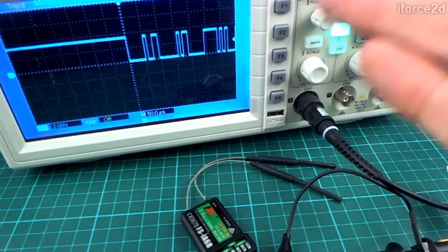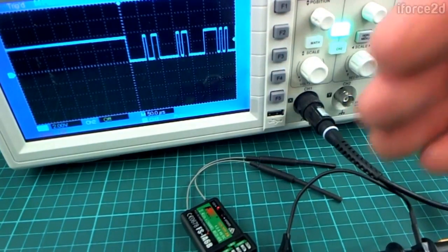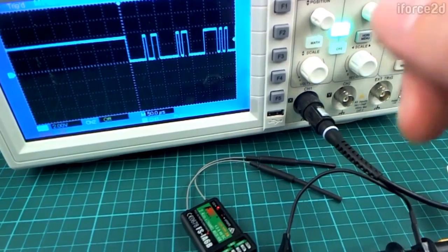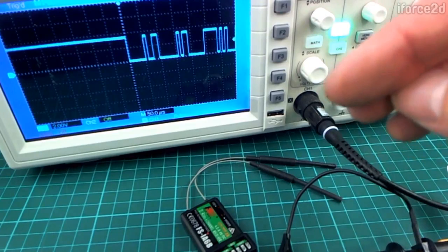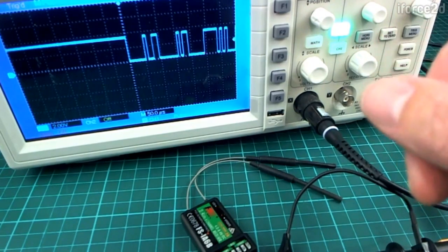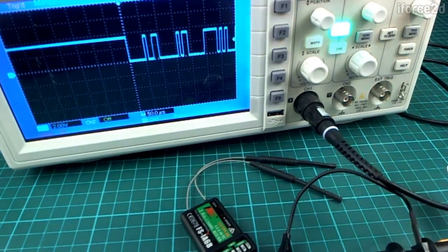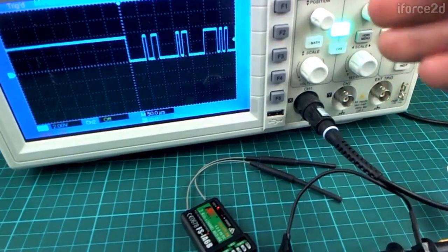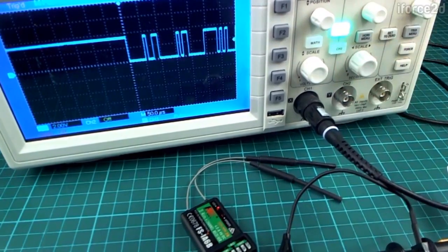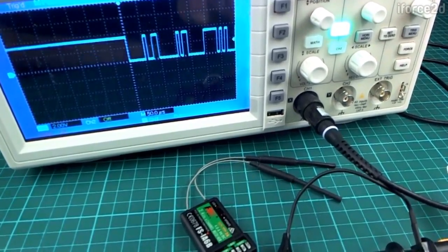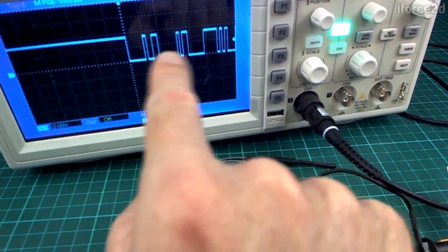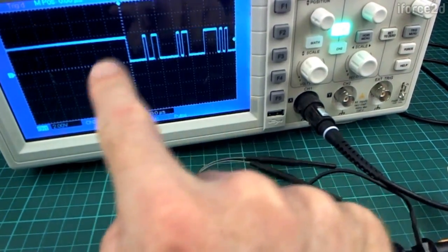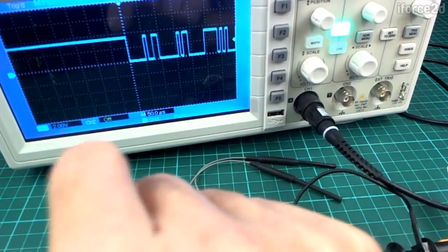And the way that PPM works is, when your friend sees the flashlight turn on, he will start a stopwatch, and then when he sees the light turn off, he'll look at how much time has passed. So that's how PPM works, and that's why it's not quite accurate if your friend's stopwatch is running a little bit different, or he pushes the button a little bit too slow. The number that you put in is not going to be exactly what he gets out. But the way serial works is you can actually get exactly the number out that you put in, but it requires this binary protocol.